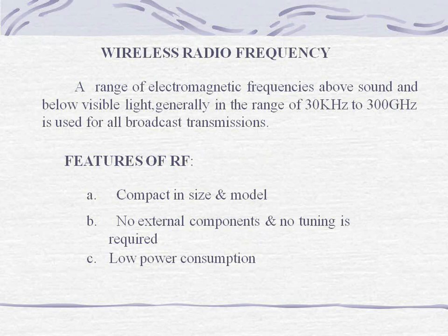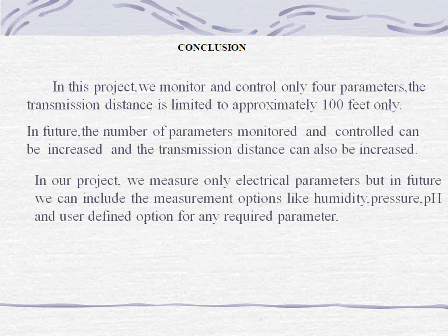For this model, we have used a 0.6 ohm 30 watts shorting resistor, called a burden resistor. For different loads, we have arranged a bulb load, called load banks. Each bulb of 100 watts is connected, and different load scenarios are created by using switches. Different loading conditions are generated, with the various values of current readings displayed in the LCD module connected to the microcontroller.